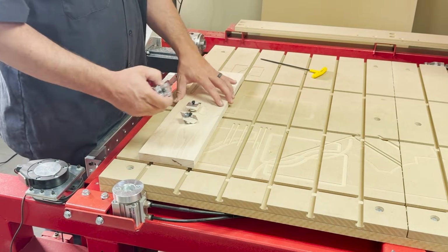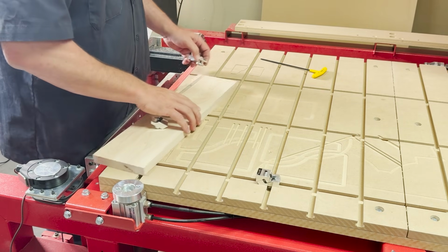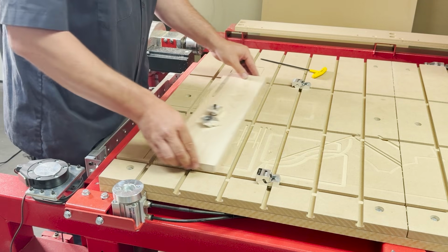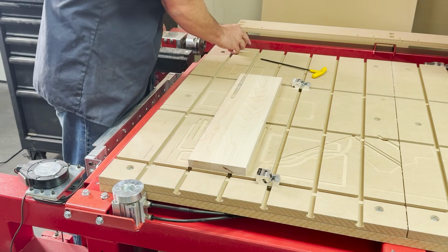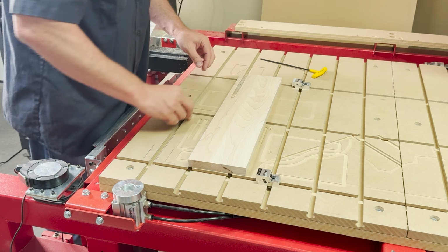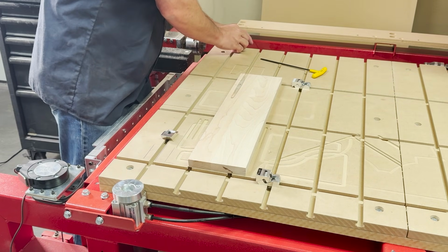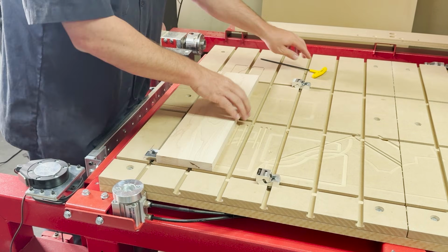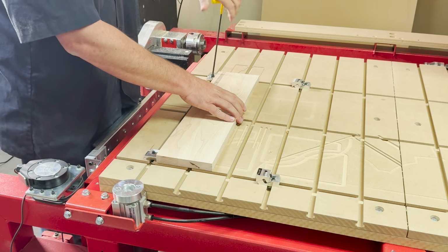We're going to start by putting the low pro clamp in. We're going to slide these on the vertical pieces here. Now once they're up and out of the way, I'm going to take my backer blocks, and they're actually going to come in on the horizontal. And the reason we do them on the horizontal is because now I've got a hard stop for these to go against. So these are going to come down here. This will lock into place. And I'm going to go ahead and just snug up these right here.